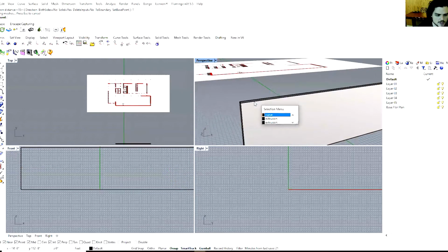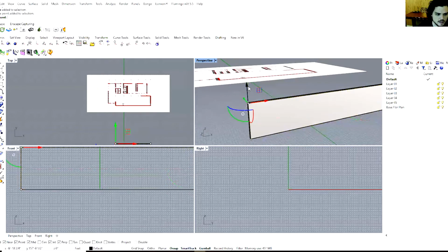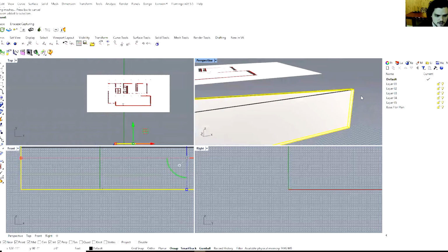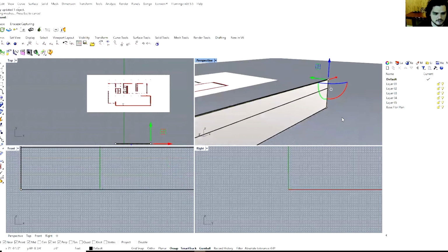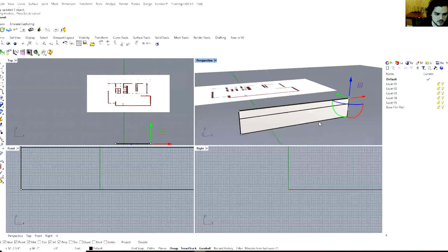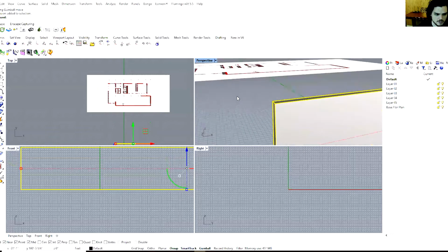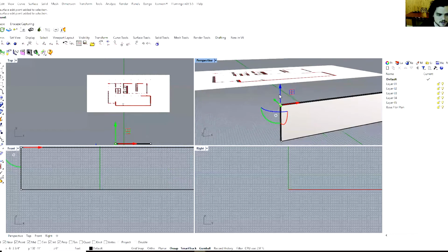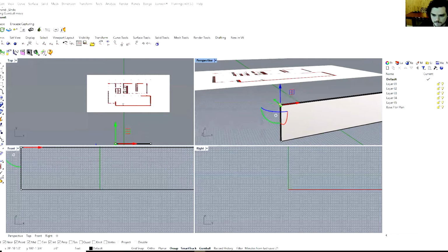The reason why I like this so much is instead of manipulating the geometry, you can come here and manipulate the line work. This proves to be a much easier way to manipulate the poly surfaces rather than afterwards having to come here and you would typically press solid point on, select 2 curves and extrude. And then you also break your history with the object.